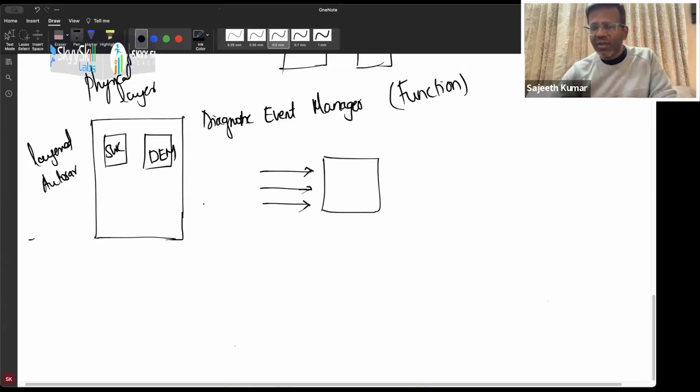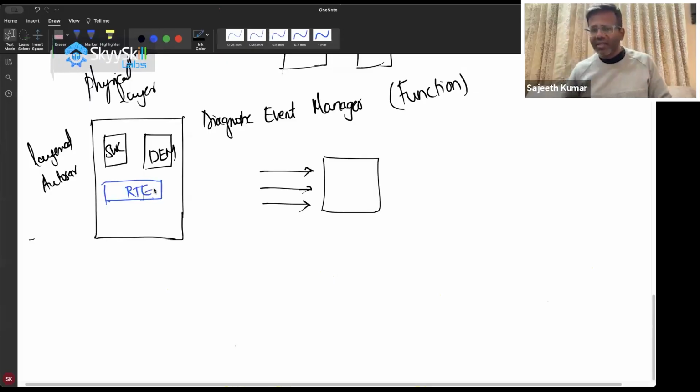It's not physical IO, it is just messages which are coming in. So any message that comes in, it can basically read those messages. Technically speaking, there is something called an RTE layer which sits here, right? So it's not directly reading the CAN messages, but there's an ISO-TP, CAN-TP. It comes through there. There's an RTE layer, but let's assume that we are able to send the signals. It is able to read it, right?